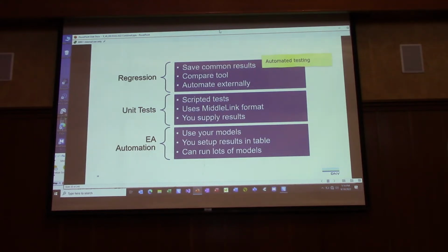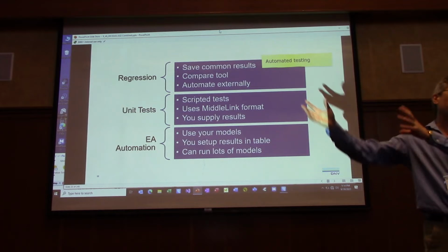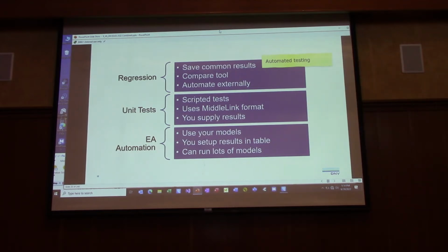That's where these single-phase lines come off and they run through neighborhoods and they come back and form three-phase lines and go on. It's difficult to run fault analysis on these because we can't just add up the impedance, so we have to calculate the impedance. That means that the fault analysis runs a lot slower. So we built a new fault analysis application that is phase domain based.